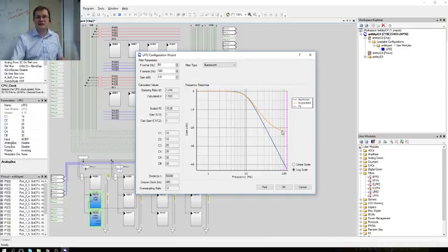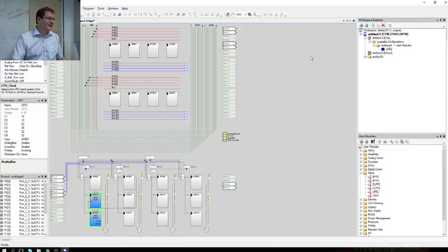You can actually test it yourself, how it functions, by taking the signal out. All right. Comparator output was also disabled. Polarity. So basically, this is using Sallen-Key kind of design, either inverting or non-inverting output polarity. To get positive output from positive signals, you check the non-inverting.